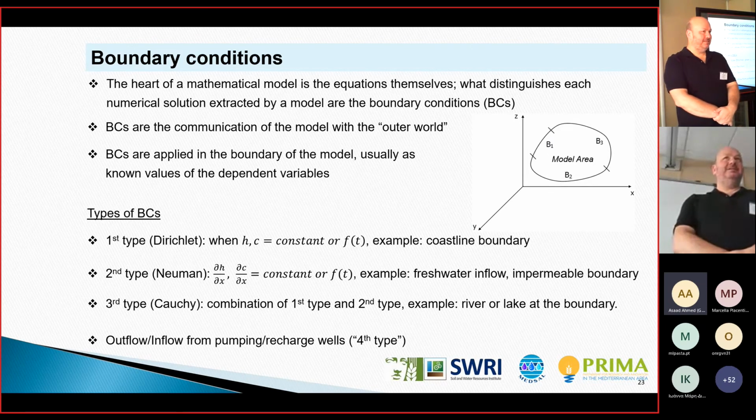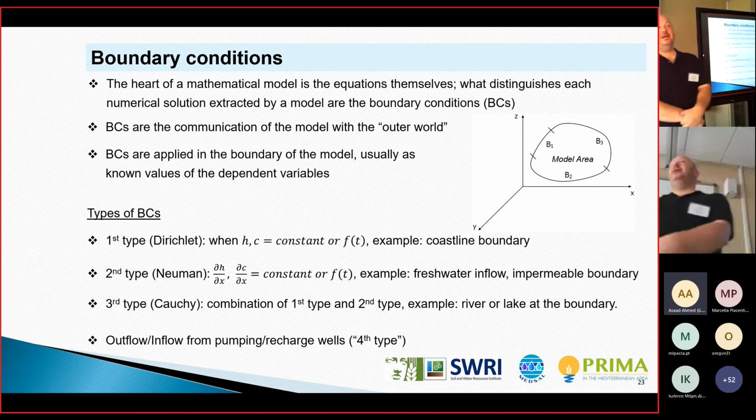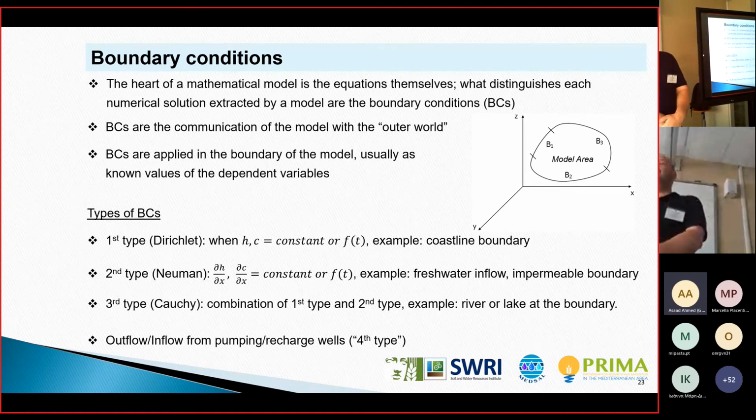Let's say, if you want to know from a model the concentration pumped from a borehole, if you need this information from the model, you have to go to the transition zone approach. If you don't care about this and you need a quick answer, where is the interface? Is it 10 kilometers from here, and you're not interested in details? Then you can apply an analytical solution based on the sharp interface approximation or a numerical solution. Okay.